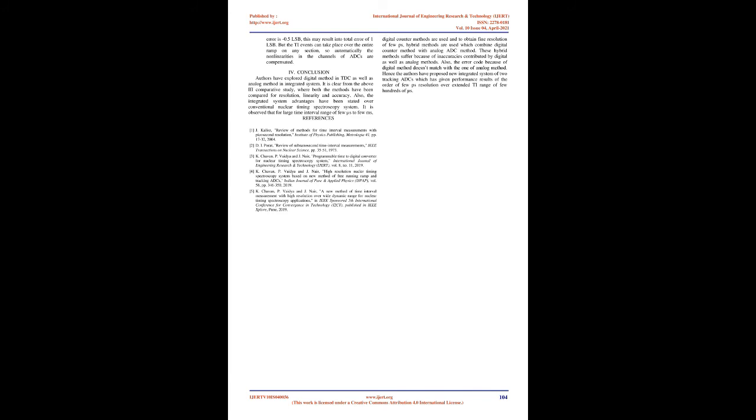In the TDC method, the input TI is converted into an equivalent ramp of time period T1 and this period is elongated to a time period of T2. Because of resistors' and capacitors' sensitivity towards temperature, the slope of the ramp may vary. But if the ramp slope decreases for the T1 period, then the ramp slope decreases in the same proportion for the T2 period. This has been proved in terms of mathematical equations in 3. Hence it is shown that in the TDC method, TI measurement is not affected by ramp nonlinearity or temperature effect.